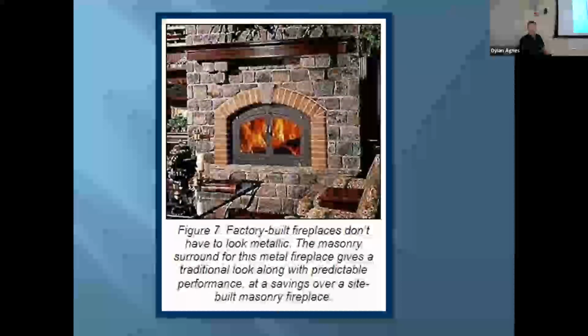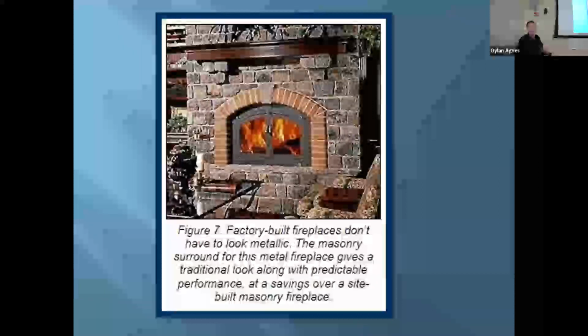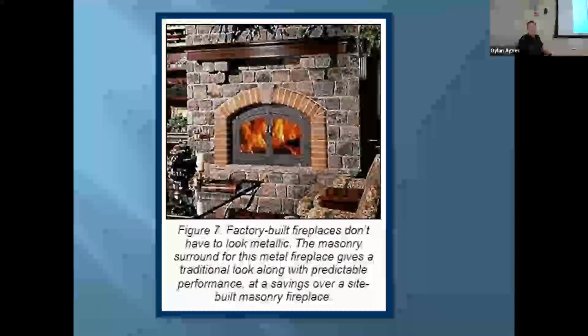This is a factory built fireplace where you go online and order everything. The fireplace comes as a unit. It's usually multiple pieces that get cemented together, and then they can finish it out any way that you want. But the nice thing with these is the doors are already built and attached, and you stamp the structure in, and then your rock guy can come in and do whatever he needs to do over the top of them. So this is not a bad option. We see quite a few of these going in.